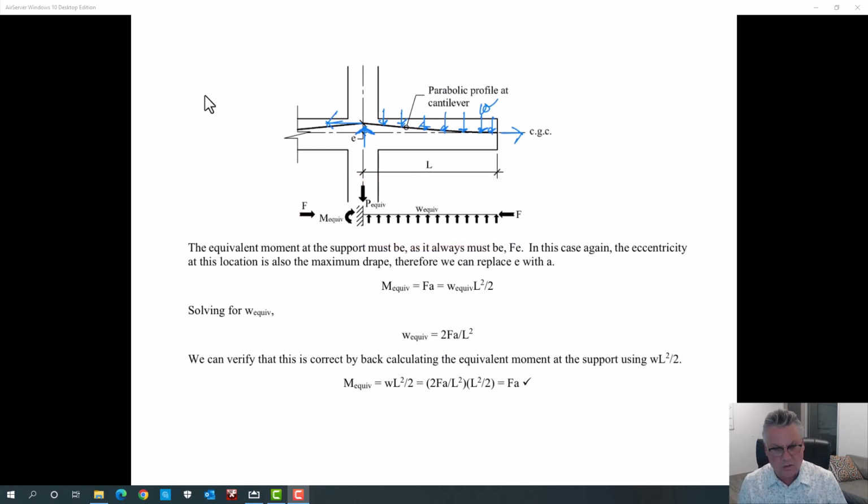So this is what the concrete is feeling, and that's kind of our primary goal, is to get all these loads acting on the concrete, because the end game here is to figure out what the stress is in the concrete. We really know what the stress is in the tendons because we put it there. We stress those tendons. The tendon group is in tension. It's got some equivalent loads on it holding it in shape, but that's a pretty straightforward part of it: we put the tendons in tension by stressing them. The real question is, what is that doing to the concrete?